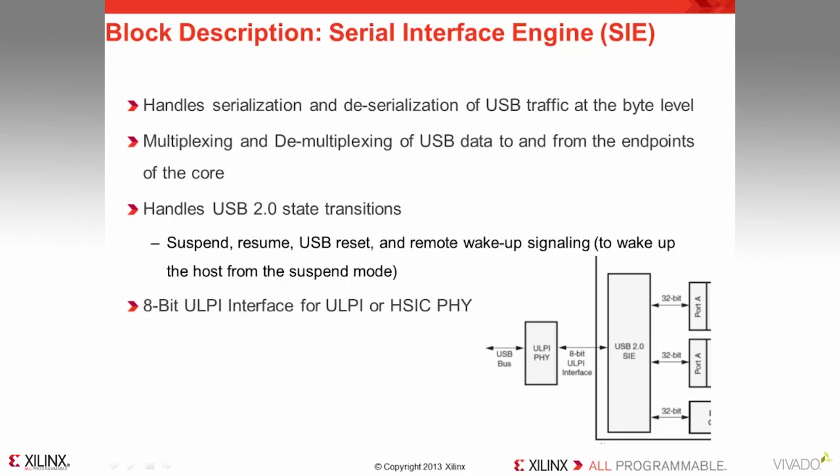SIE, Serial Interface Engine. This is the block of logic which handles serialization and deserialization of USB traffic at the byte level. Multiplexing and demultiplexing of USB data to and from endpoints of the core. It handles USB 2.0 state transitions such as suspend, resume, USB reset, and remote wake up signals.